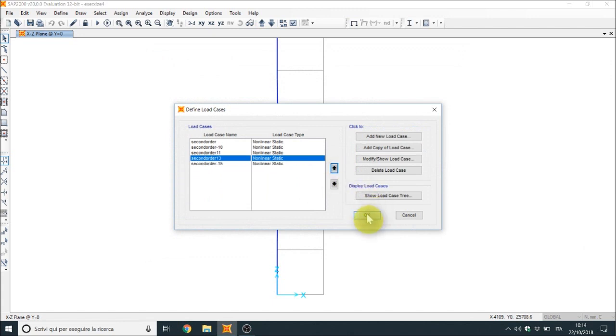So I created an iterative analysis manually, by manually putting in the vertical load that increments step by step. You can also do this kind of analysis automatically. It's a multi-step analysis created by hand, but you can also do it automatically in the software by changing that parameter that I left at default.